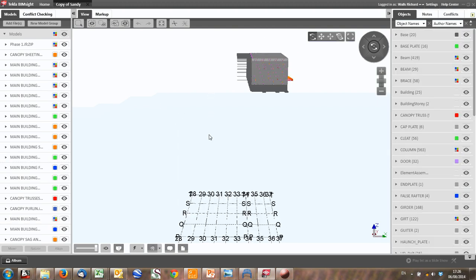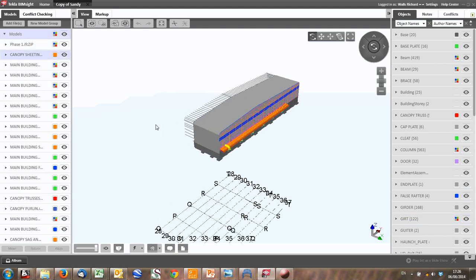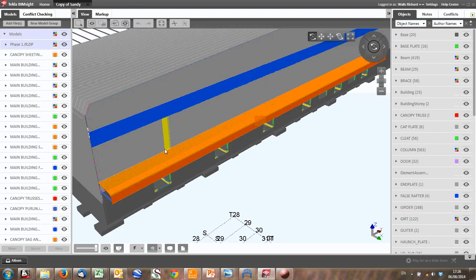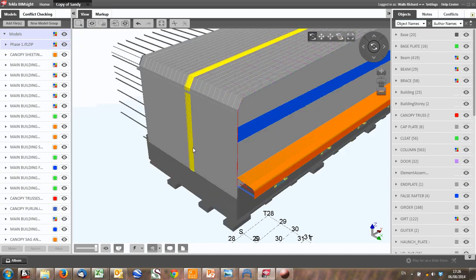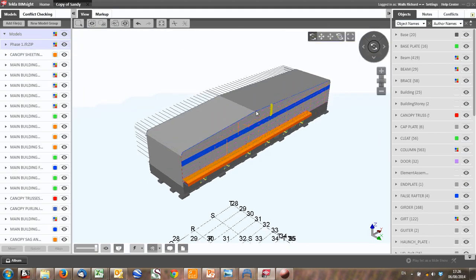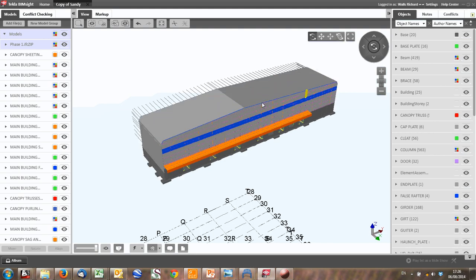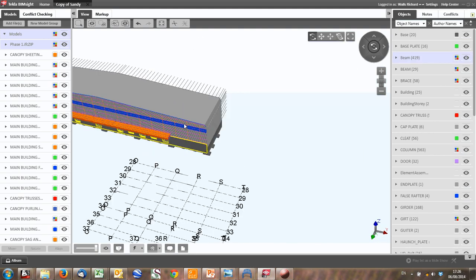There we go. Here is our model. And what's quite nice is you can actually see there's our sheeting. So you can imagine wind coming on, hitting the sheeting from this side, or wind coming on, hitting the sheeting. And just be careful on these big warehouses. Have a look at the wind load code. You also have to consider friction forces on top. Friction forces come and they are generated as the wind travels across. You may need to add those as horizontal loads.